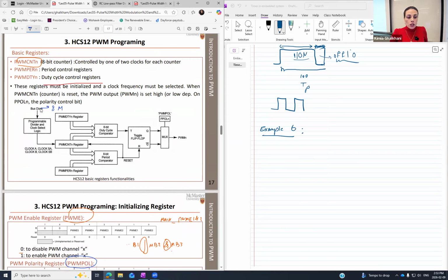And then I'm asking for the duty cycle. PWM register for the duty cycle. Remember the question was 10 microseconds. And then I'm supposed to look at the divisor. This is what I'm going to calculate. So I'm going to send the 8 to the divisor, to the divider. The total divisor in here should just send some information to my CNT. Remember I said this is going to stand for the counter. And then what I'm going to have from the PWM PER register, I'm going to have 20 kilohertz right in here. This is the plan, right?